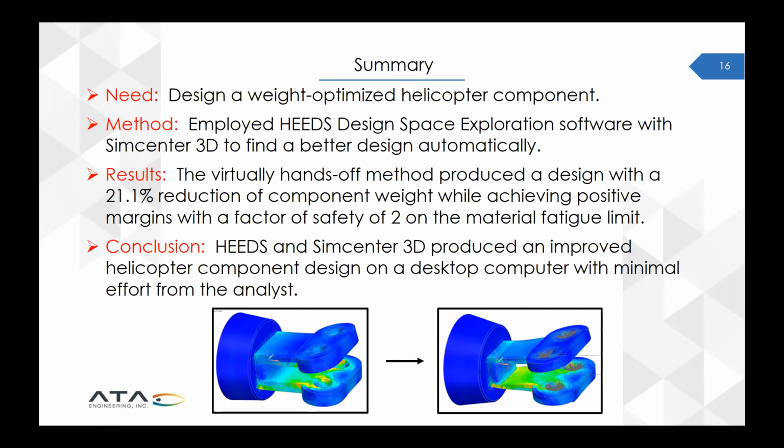So in your case, you morph the mesh, then you don't remesh, because if you remesh, then the mesh element IDs go all over the place. They don't stay constant. Right, yes. As I was saying that, I realized that that would be an issue. So that would be something that I'd have to look at in Simcenter 3D, but I'm sure that there would be a way to spatially filter it so that these hotspots did not pop up in the results that were passed to HEEDS.